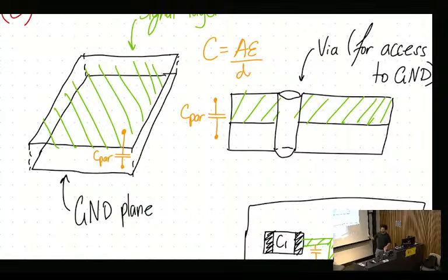So reduce the area. Under any particular node where we're really concerned about this parasitic capacitance, we just remove the ground plane around it. That ensures there's a return path to wherever the ground is not directly underneath. So there's no capacitance directly under whatever node we want to reduce the parasitics of. Does that make sense? And so I'll draw the PCB that it's asking for.